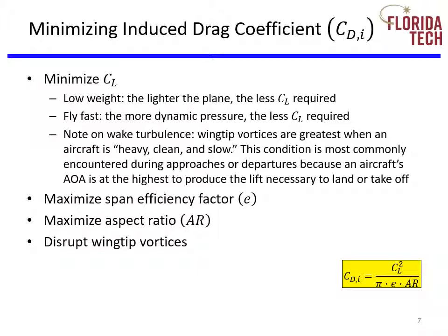Put the two of these things together. Where are wingtip vortices the strongest and induced drag the greatest? The answer is on takeoff. The airplane is heavy, it's flying slowly, and it's generating extra lift to climb. This is the key reason for traffic spacing at airports. An aircraft taking off needs to give the vortices from the aircraft in front of it the chance to dissipate. Getting caught in another plane's vortices can be disastrous.